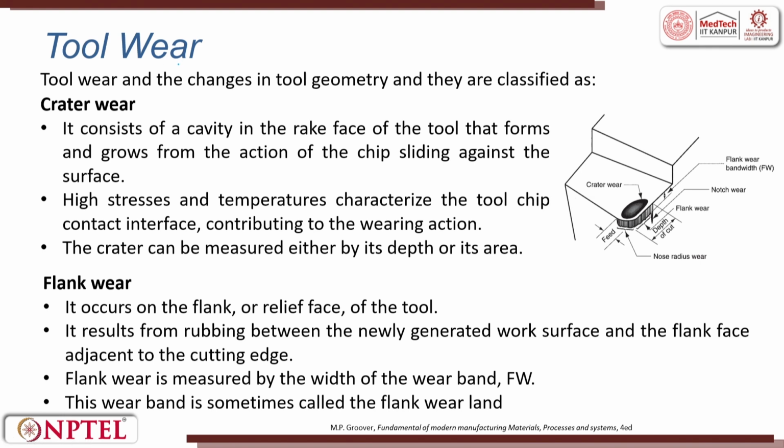Generally, in a tool we have crater wear and flank wear. Crater wear happens along the rake face. The flank wear happens along the cutting edge. Crater wear consists of a cavity in the rake face of the tool that forms and grows from the action of chip sliding against the surface. The high stress and temperature characterize the tool-chip interface, contributing to the wear action.